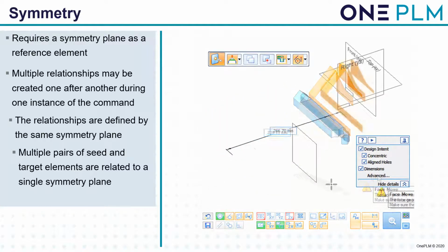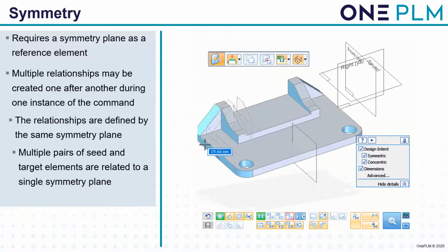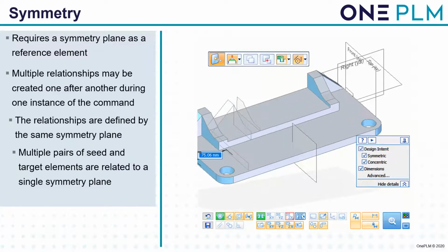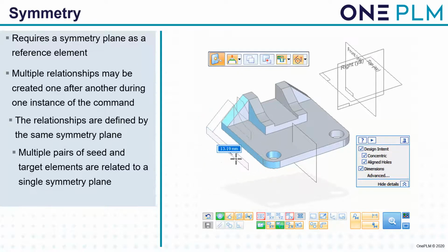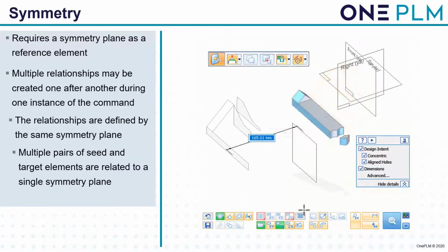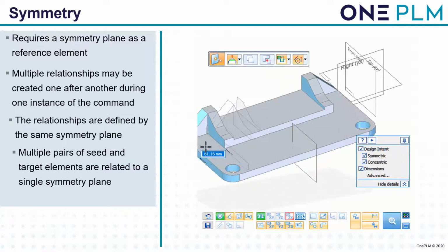What we do, we select the faces we want to move, start to move them, and then notice we haven't got any symmetry on there. So we click the advanced option, the design intent, and then click the symmetry option that is available on there. So let's just have a look at that. Moving that side, no symmetry. Click on advanced, this box pops up, and we can click that little option and then click that plane. That's now going around that plane on there.